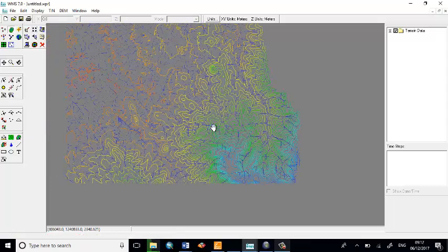So here, now you can generate your watershed. But what I have told you before, in Global Mapper, you cannot use an outlet point. Here, you can use your outlet point. You see here, this is create outlet point. When you click create outlet point, the plus sign will be shown like this. Then click somewhere else. When you click somewhere else, have you seen these things?